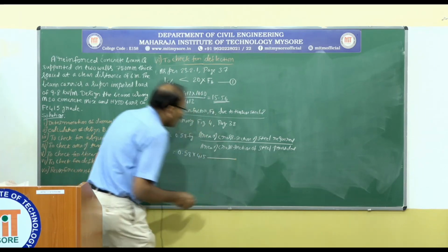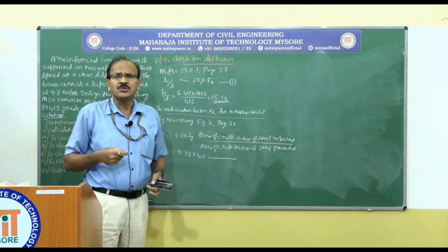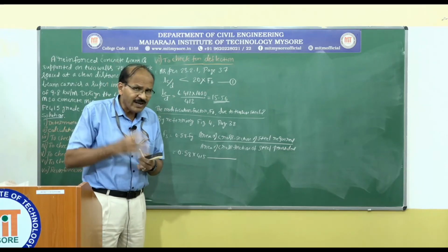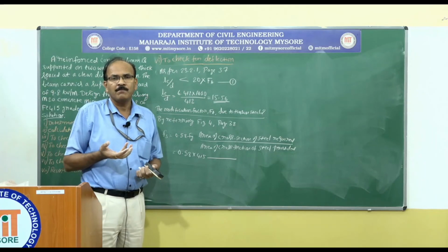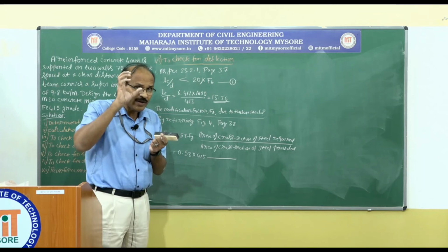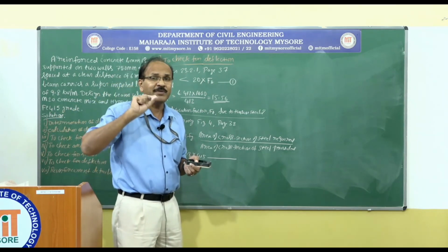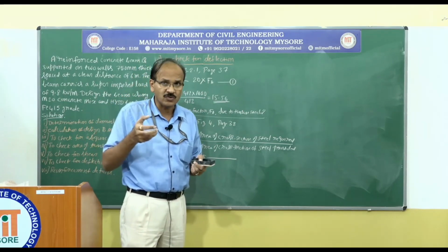Okay. So what is the area of cross section of steel required? If you go back to the calculation of steel, Ast, what was the value we got? 786.44 millimeter square. Then we divided that by the area of cross section of a 20 millimeter diameter bar, that is pi by 4, 20 square.